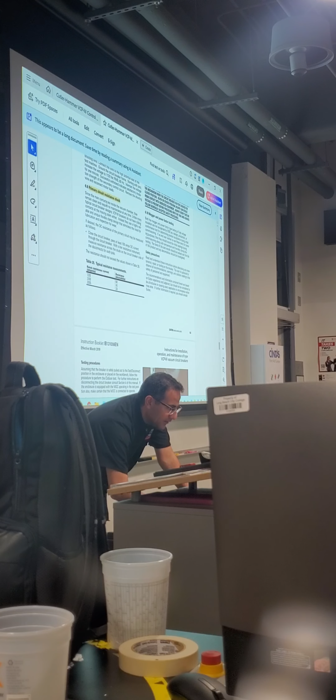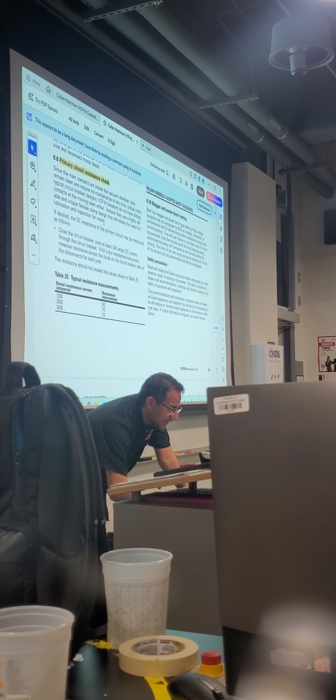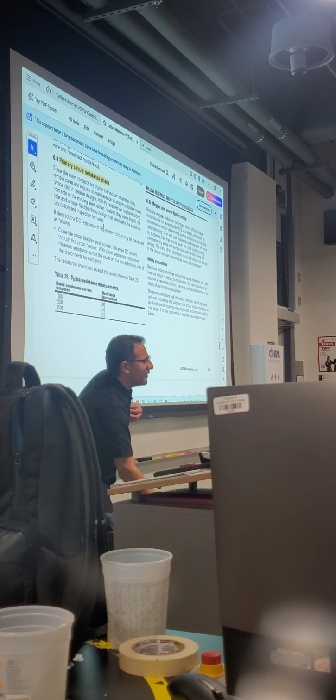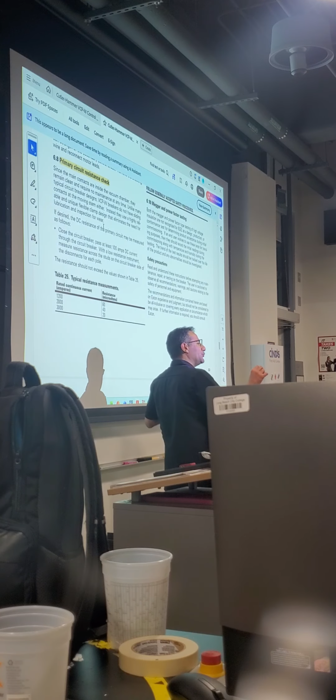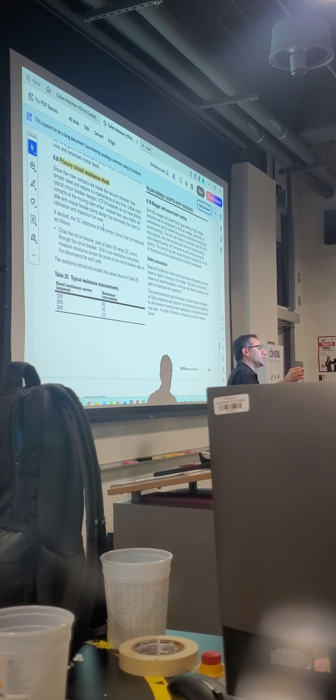Oh yeah, for the primary circuit resistance check. In NIRA MTS, any section that you go to, they tell you to refer to manufacturer documents. In the absence of manufacturer documents, apply the 50% rule for the DLRO.